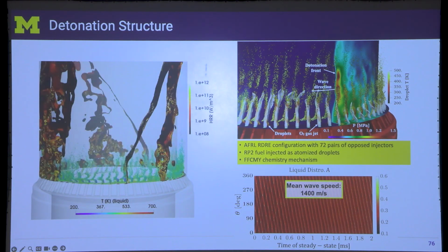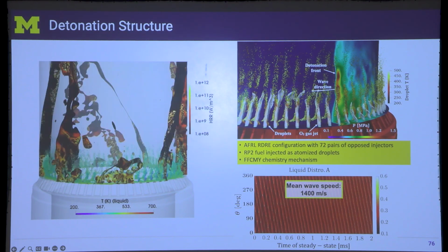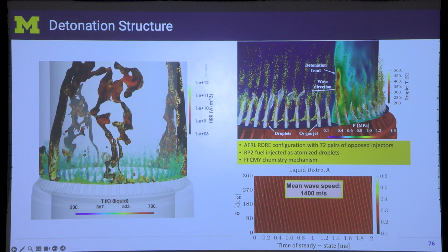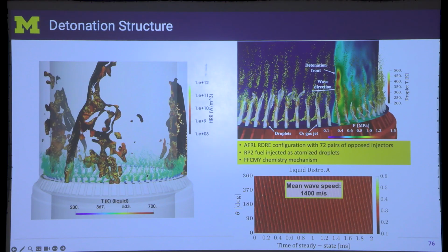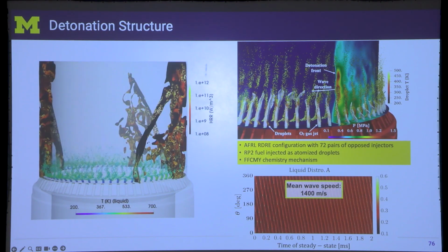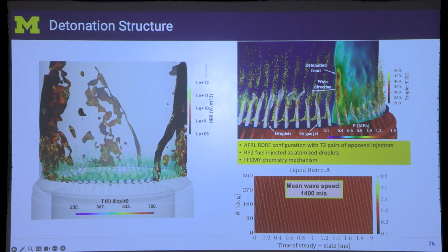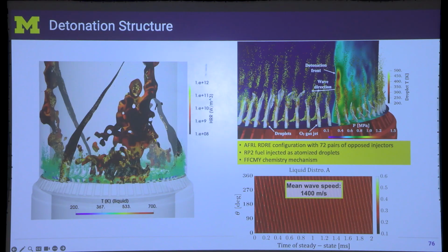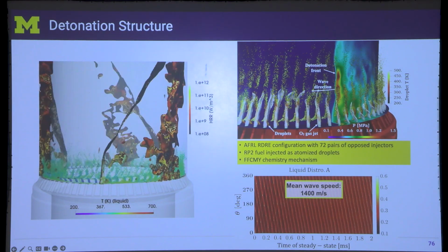The surrounding gas is now hotter, so it's going to start evaporating faster. But what you will see is that evaporation rate, what is called D squared law, is not very fast. In fact, it will take about half of the cycle time, half of the time for the wave to go around the circle before these droplets will fully evaporate, which is too long. That shock wave is spanning about 5 degrees. That's the detonation wave structure out of 360 degrees, okay? And I'm telling you that these droplets take 180 degrees of the shock wave before they will evaporate, which means they are not within this detonation structure at all. The high temperature is making them evaporate, but they are not the ones driving this whole shock structure, which is very confounding. This is not what we would expect.